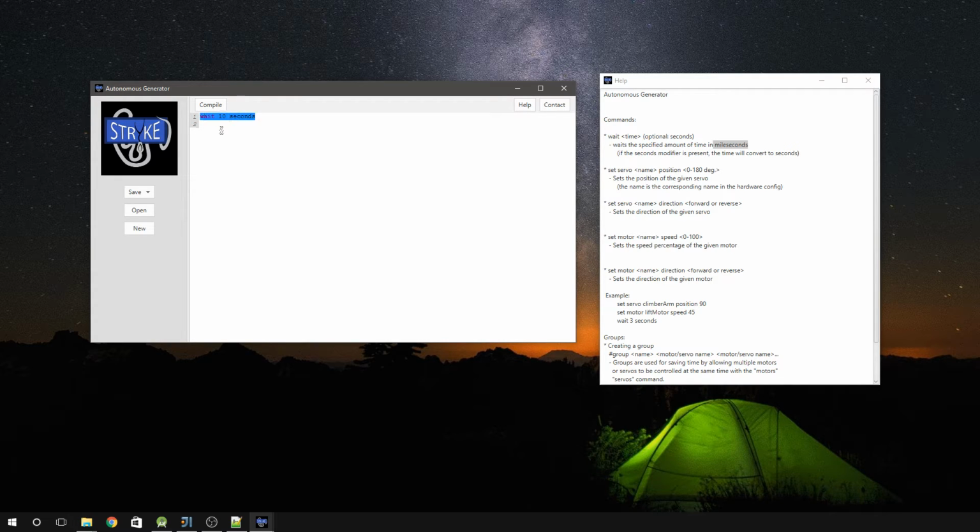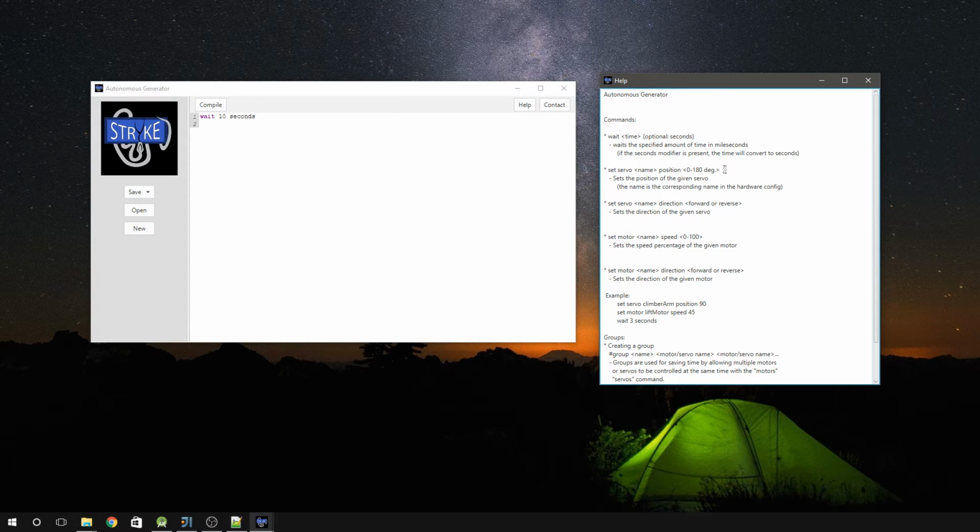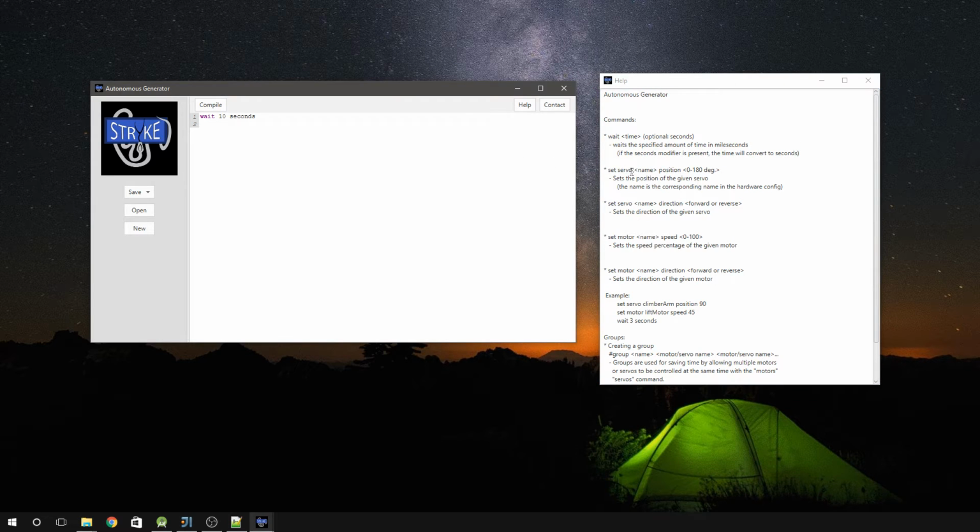What this will do is wait 10 seconds in order for that first bell to ring, where your robot is allowed to cross over to the other team's line zone without getting a major penalty. And this can be very helpful if your robot is prone to getting knocked off course by debris. So we're just going to write a very simple autonomous program with this.